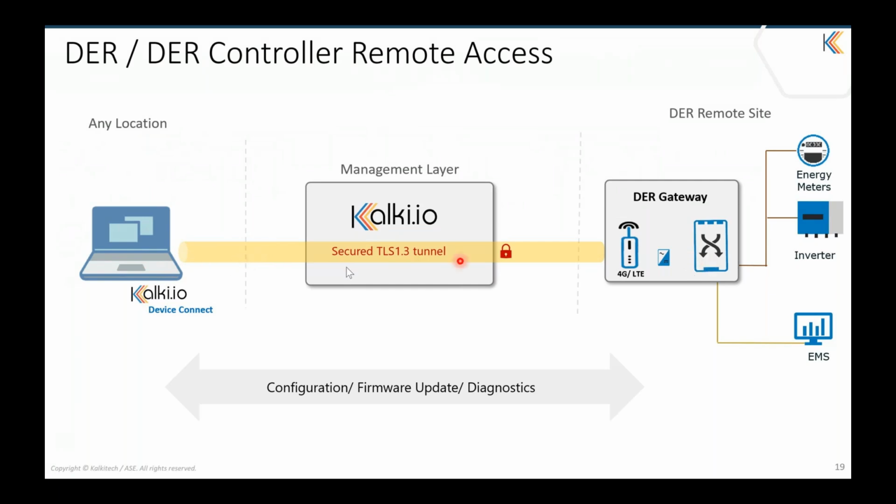And through this secure TLS 1.3 tunnel, you can access any of these field devices remotely and securely, and do all the use case requirements, like if you want to do the configuration update of the devices, or firmware update, or diagnostics of devices, it can be done remotely from the technician PC over a secure link.